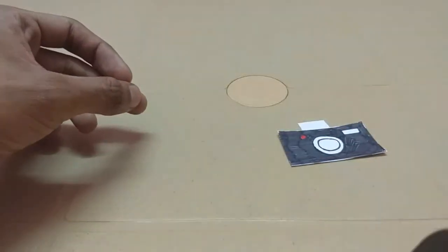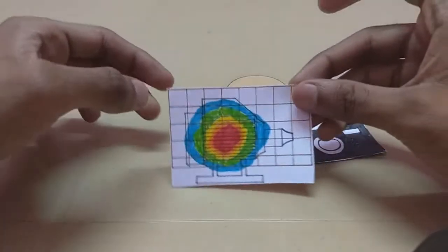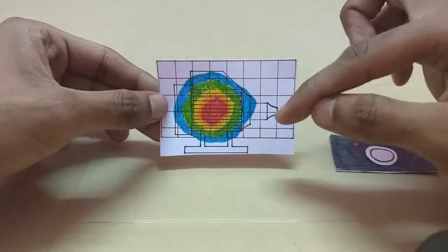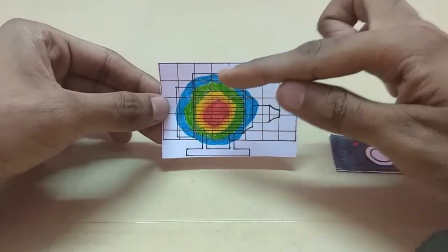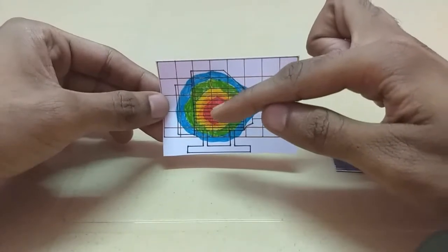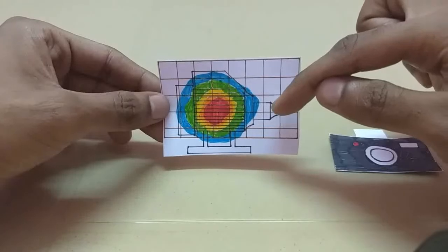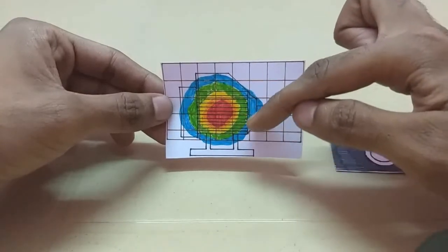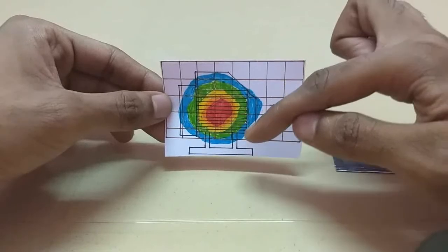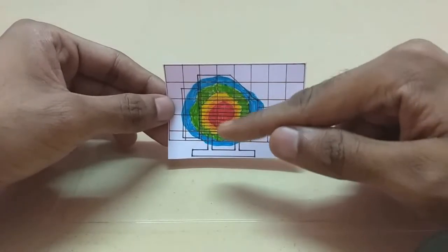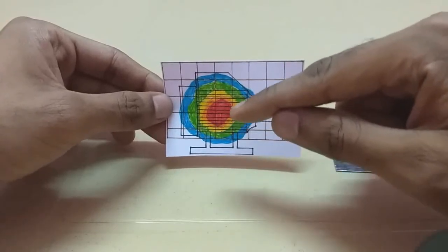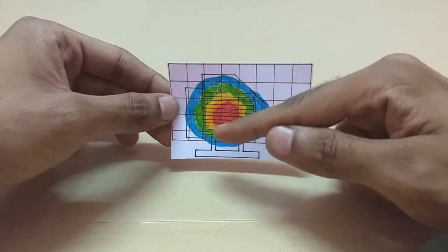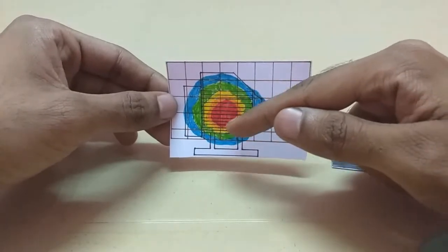Now you press the analysis and the software will do the analysis. The analysis will look something like this. Now this is the contour plot, meaning you're able to see the machine and you're also able to see the intensity. Red represents maximum intensity, and as the colors get cooler and cooler toward blue, it represents minimum intensity. Now if you study here, this region has the maximum intensity, and these regions are very, very less intense. So now you can narrow it down. Okay, the source responsible for creating noise is right here. Now this is a simple case. It's just a single pump, and you have a simple impeller inside. So obviously this is the expected source of noise.